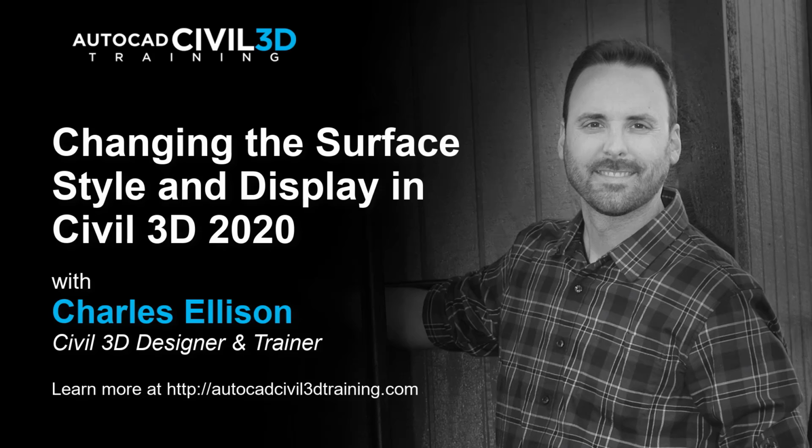Using styles is an efficient way to control surface display. Rather than answering prompts for numerous variables every time you create a surface, you can reference a predefined style that sets all of the variables as required. Surface styles are managed the way all object styles are managed in Civil 3D, by using the Toolspace settings tree. All objects have a standard object style grouping on this settings tree called the object style collection. You can create, edit, copy, and delete the styles for an object.